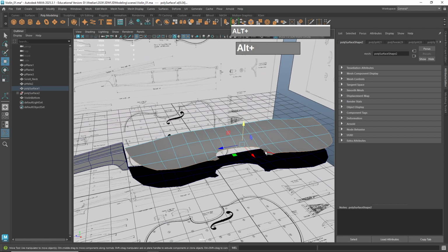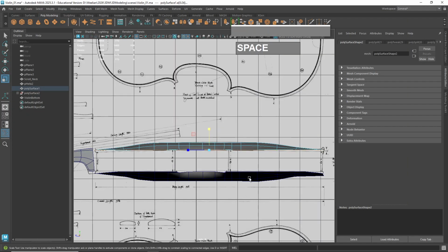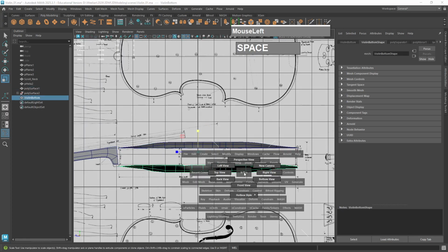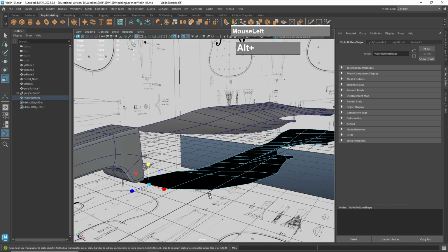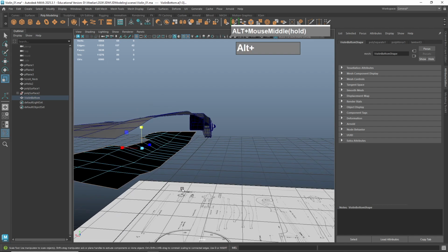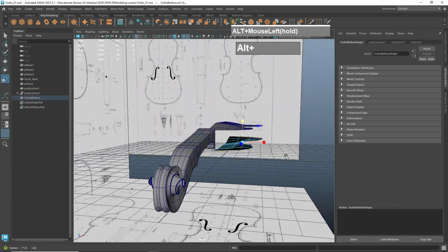Now before I do that, let me scale and flatten it like that first. Okay, so now it's nice and flat. I'm going to do the same for the bottom one here as well, for the edge. Actually, just double click to select the open edge, and then we will deselect the center. So holding down control and just drag the box over the edges in the center line that you don't want to select. Then scale and then flatten it, like so.